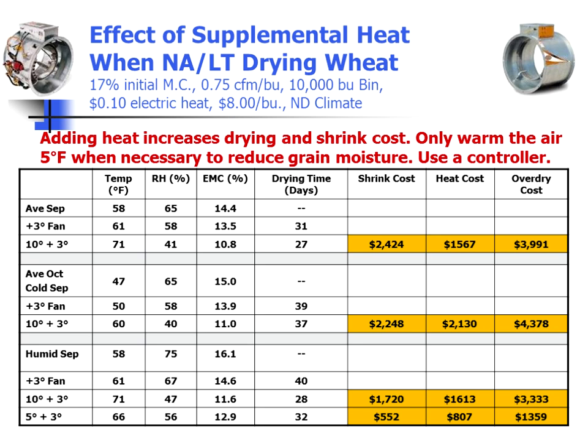Even as we go into an average October or cold September in our climate, if we're looking at adding 10 degrees of supplemental heat, we're still looking at over-drying the wheat, and we're looking at some pretty substantial costs. If we're looking at very humid September conditions, maybe the fan heat doesn't quite get us down to the moisture content we want.